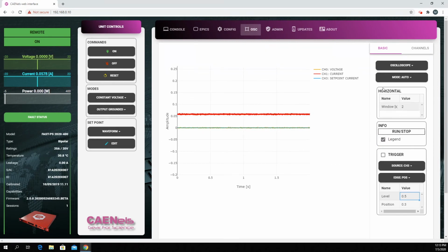And going back in reverse here, you would have the sampling window on the horizontal scale. So right now it's set to 2. Therefore, if we scroll over, you see it is up to 2 seconds. That can be changed. Put 5 seconds.